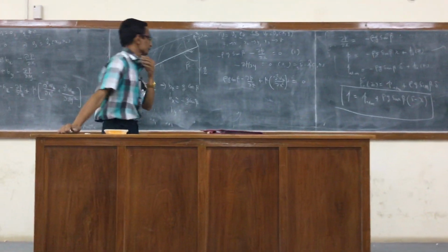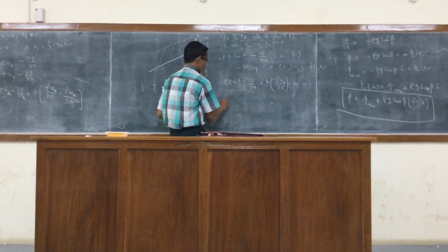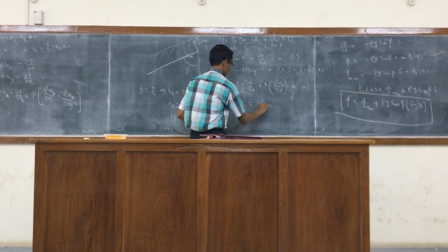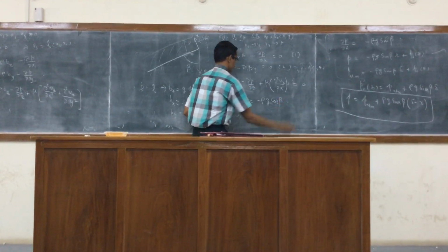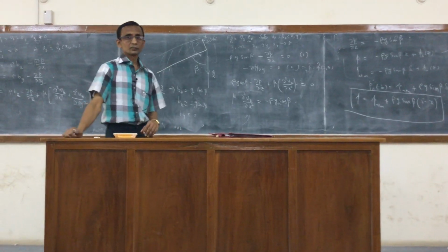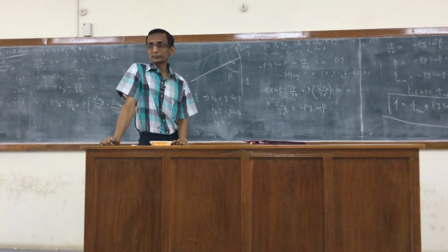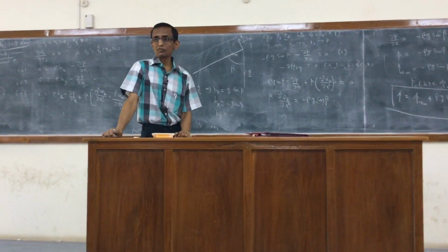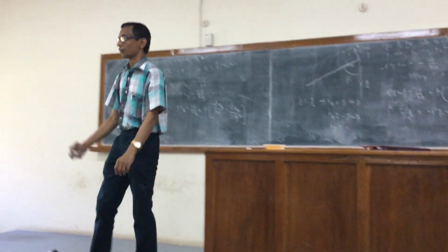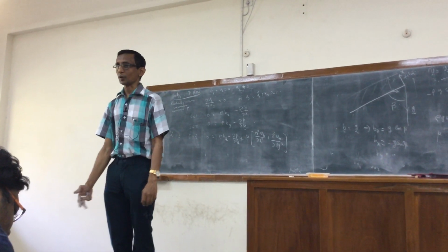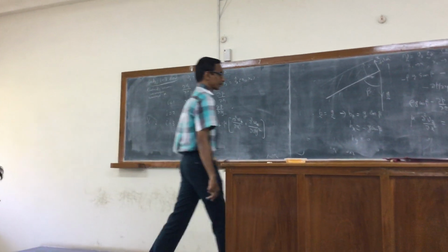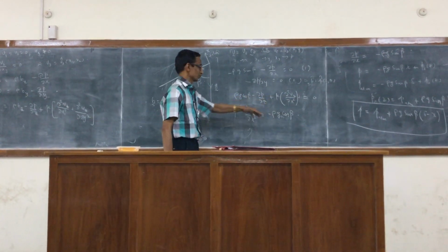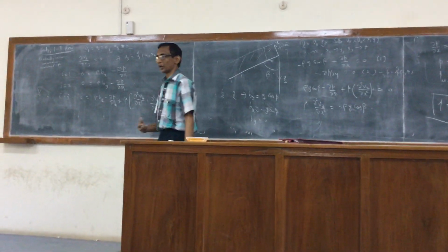So this term would vanish, and the equation simplifies to this. Because, based on the boundary condition given to us, the pressure is independent of z. It's dependent only on x, and so we finally get this very simple equation. Actually a constant coefficient equation, very, very easy to solve.